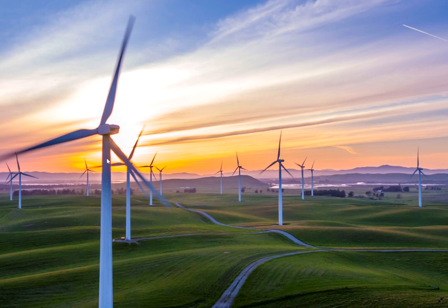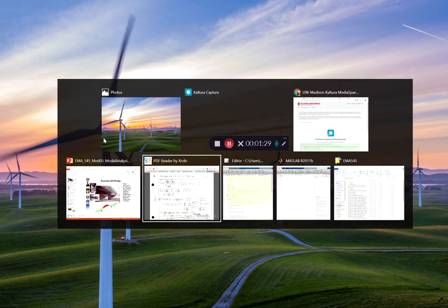So imagine that this tower is sitting here, minding its own business, and the wind blows. We could model a gust of wind as a step increase in force. In an instant, the force goes from 0 to some non-zero value that wants to bend the tower over a little bit. For a large tower that might be 100 meters tall or more, you could have maybe a meter of deflection at the top of the tower, maybe more, in a reasonable wind. So that's the problem that we're going to try to model.